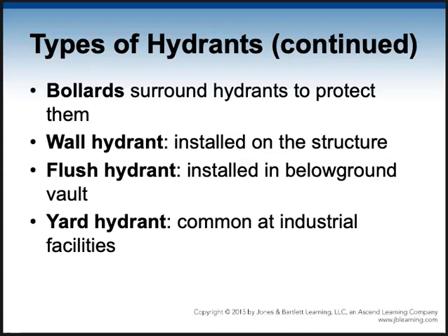So it still happens, but the bollards they'll put there to try and protect them from people hitting them, and it mostly helps. A wall hydrant is any kind of a hydrant that's installed on the structure. A flush hydrant is installed below ground in a vault and takes a special kind of device. I'll show you a picture. A yard hydrant is common in industrial areas, also where it would be below ground.